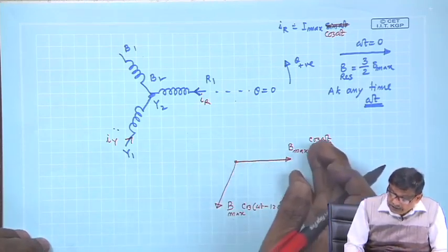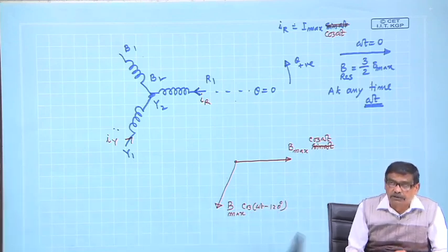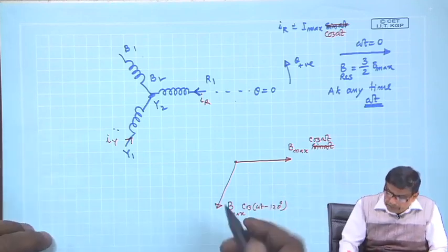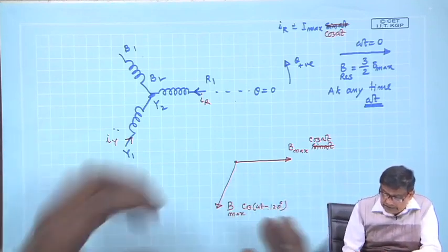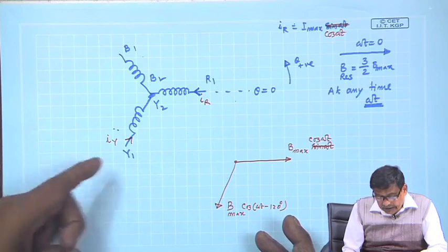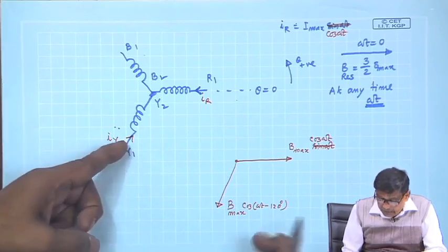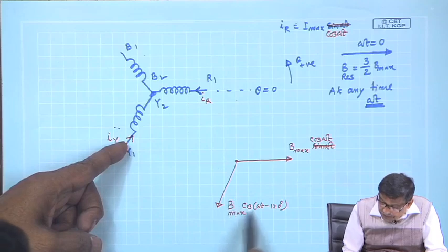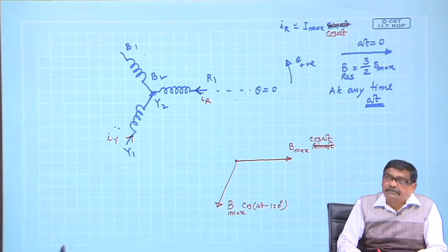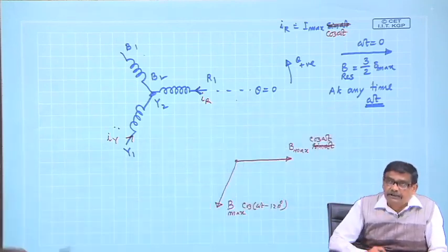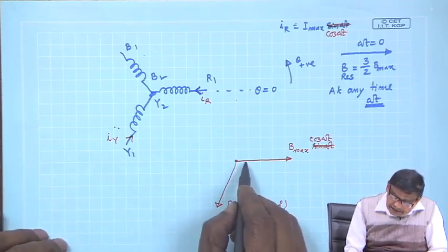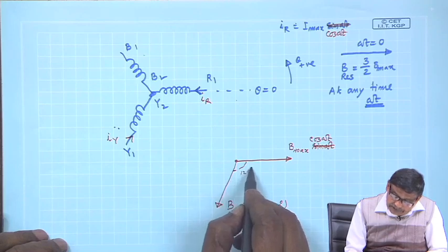They are not of equal lengths, or half, or root 3 by 2, I do not know, but arbitrarily, depending upon that instant, I should adjust this length. On top of it, this current may have a negative instantaneous value. Then this equation will give you a negative quantity, which means your B is actually opposite. So, the equation takes care of that reversal of the vectors. So, it is a sort of generalized approach, but nonetheless this angle is 120 degrees electrical.